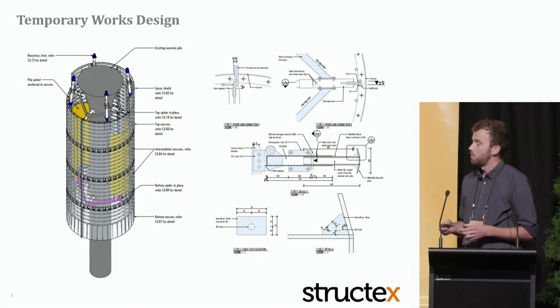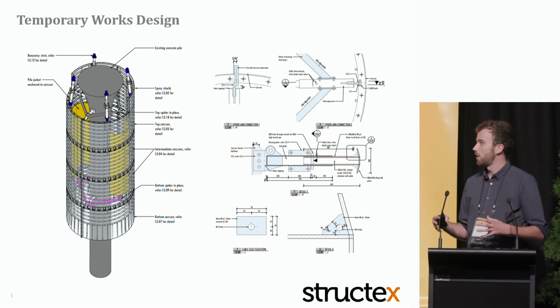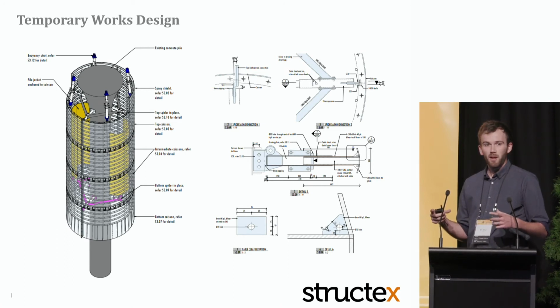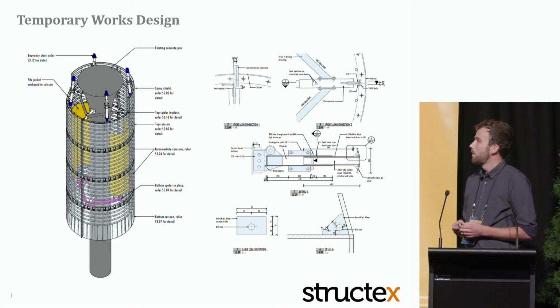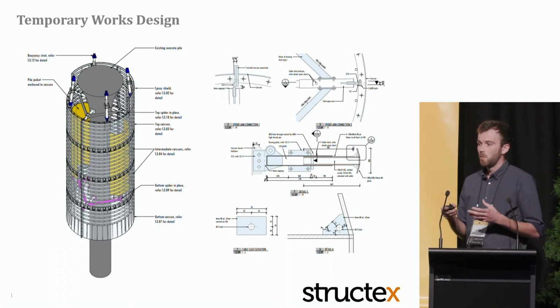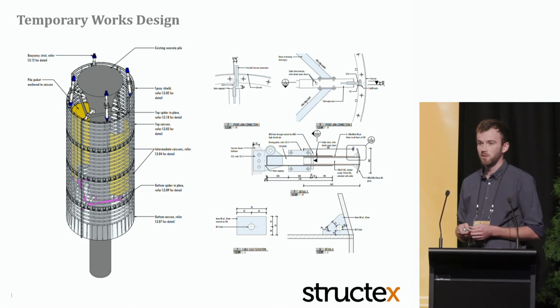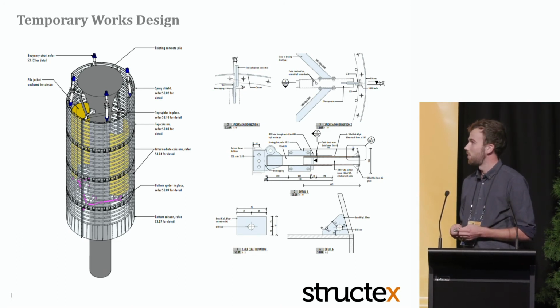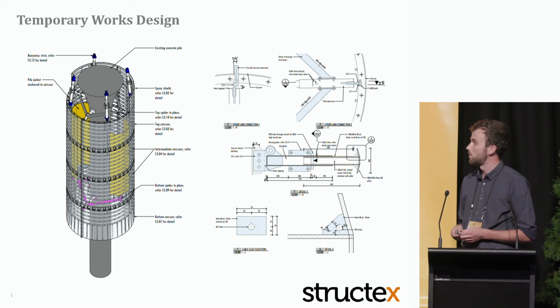We had the added complication that you're not only repairing a structure, but while you're repairing it, you're making the pile about 4 or 5 times the diameter. So considering the effect of wave loads hitting something far larger than the superstructure was designed for, how can we protect something for the future if technically it only has to be designed to a 6-month construction design working life? In this case, it was actually designed to the full working life of the superstructure.